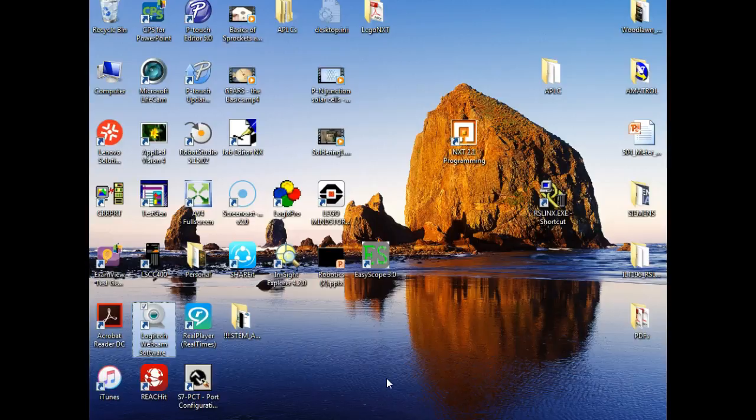But all these numbers on the top, who assigned these numbers? Can y'all see it? The manufacturer. So when we connect wires, we're going to do it by a ladder diagram. Before you connect that up, you're going to go through your print and assign the manufacturer numbers to your circuit. That way, when you hook them up, you're not trying to go between manufacturer numbers and your line diagram, because all your numbers are on your line diagram. Y'all understand manufacturer numbers.